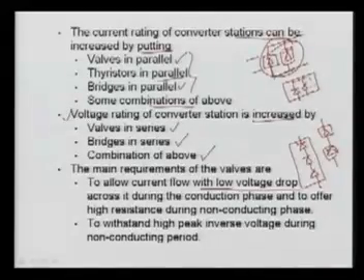Here the voltage drop must be minimum during the conduction period, and it should offer high resistance during the non-conducting phase or blocking phase. So when it is on, it's just like a short circuit; when it is off, just like an open circuit. So we want an ideal switch characteristic.